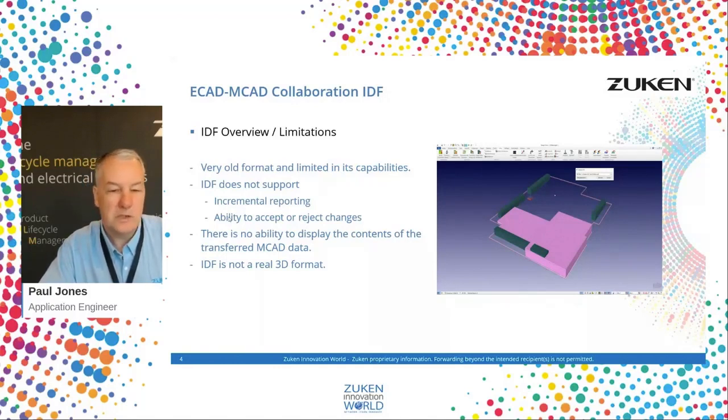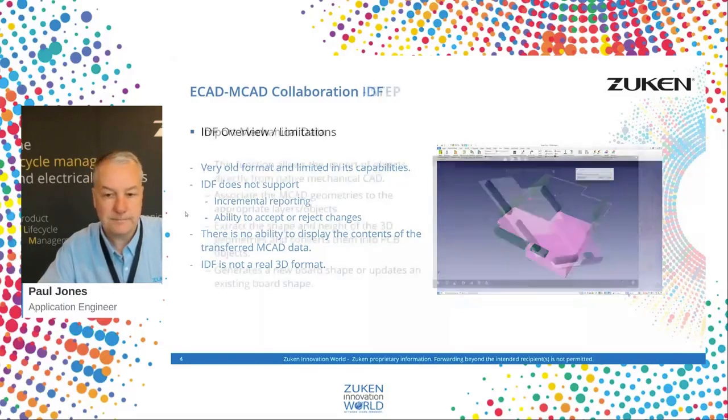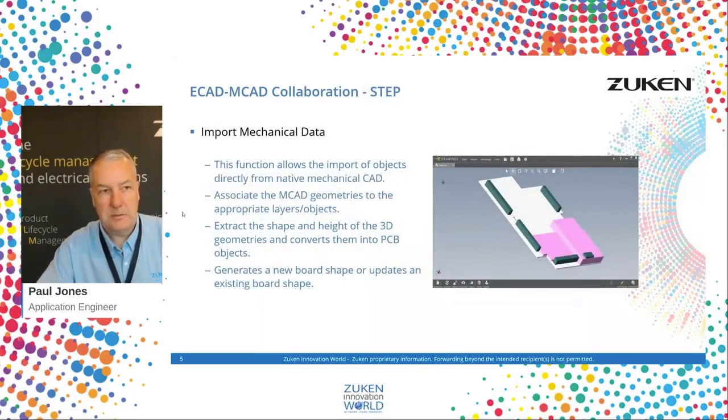And then IDF isn't real 3D format data. What I really mean by this is that, as you're aware, if you're a PCB designer or a hardware engineer doing PCB design and you're asking for IDF data from your mechanical team, it's an extra task for them. They have to draw those boxes, those squares and things like that, to actually send you the data. So it's obviously taking up more of their resources, which you don't want to do. So those are some of the limitations of IDF.